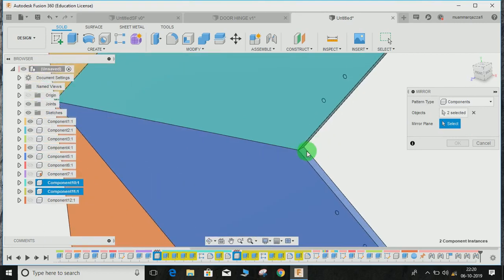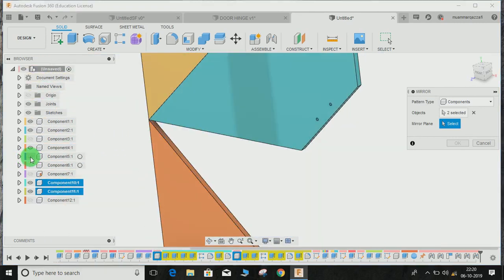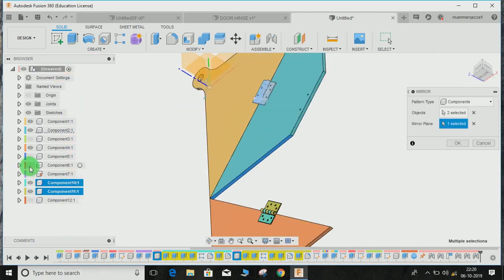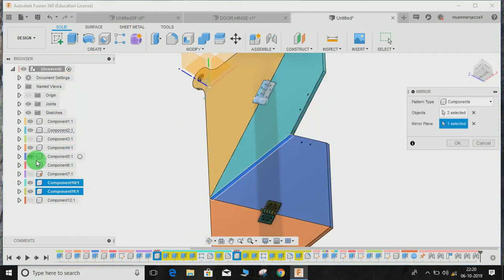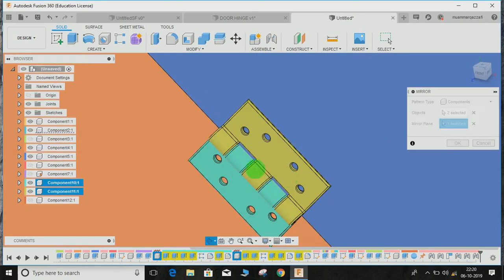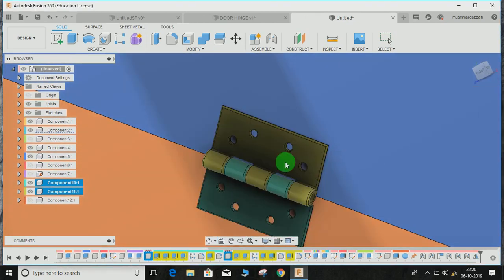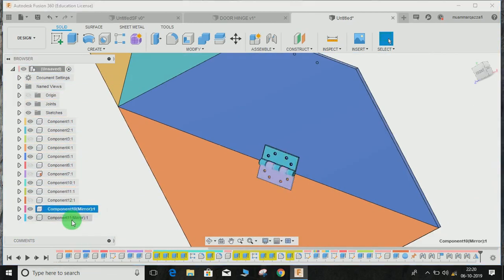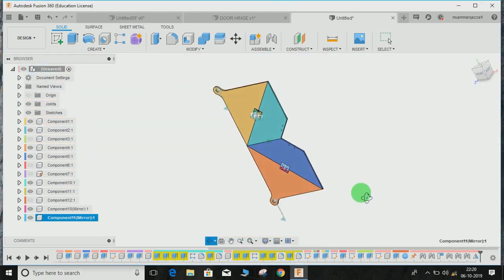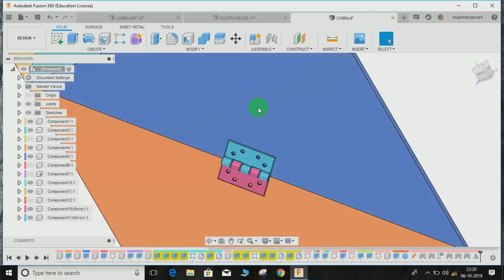Yeah, so the mirror plane is going to be this one. As you can see, this is the after image, the before image. It is actually sitting on the actual position, and press OK. Now we have two new components representing each one of the bottom. So now all you have to do is make a rigid relation between them, and this is quite simpler as they are already assembled on their desired position.